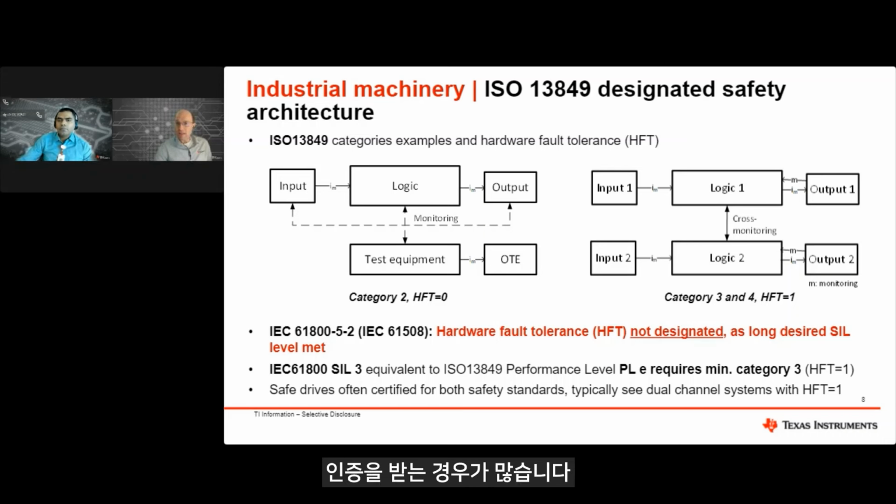Blue color tabs are the fields inside the FMEDA where your input can be customized by the system integrator. The green color tabs are the place where the results or the outputs of the FMEDA customization are reflected. Blue color tabs have fields whose values can be entered by the user. The default values of these fields can be changed based on the needs of the user application. The green tabs show the result of computation based on the choices made in the blue tabs.